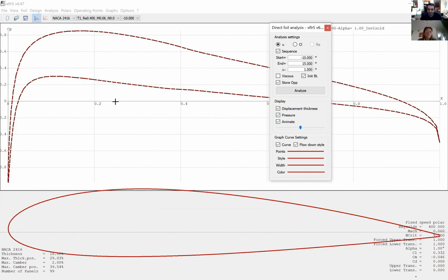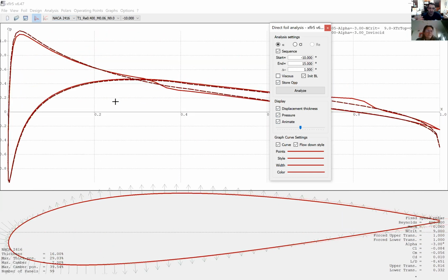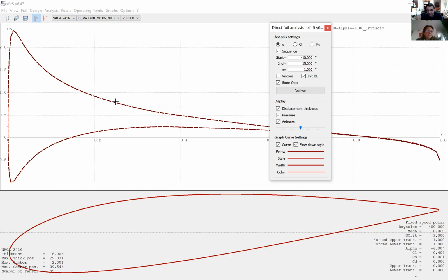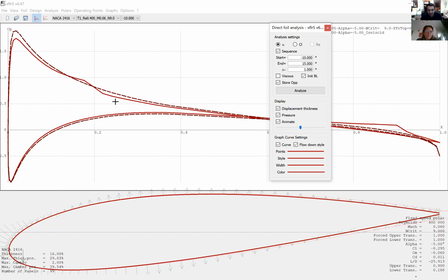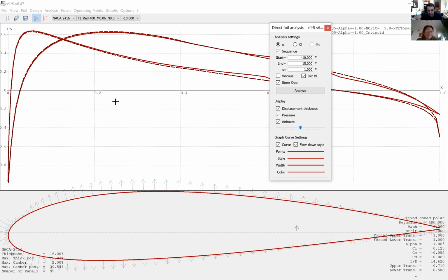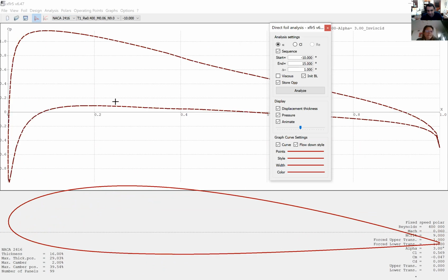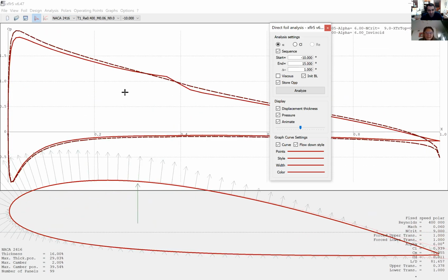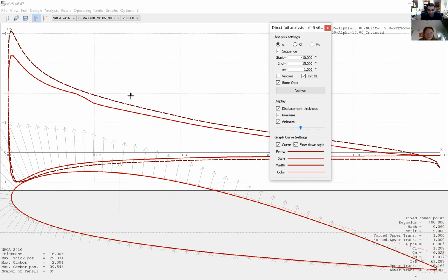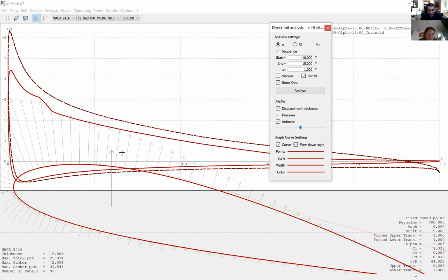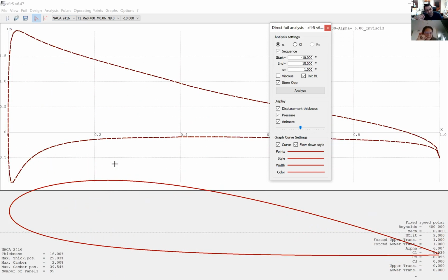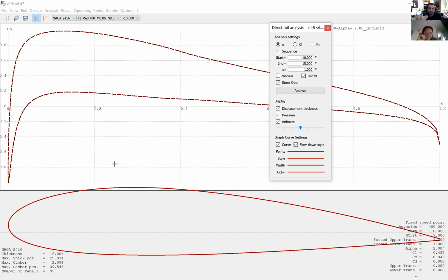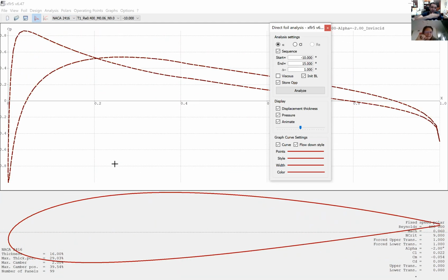With the angle of attack, the center of pressure, which is the resultant force or resultant pressure, is changing. You see that green vector at the middle of the airfoil. This is the resultant pressure, and its position is the center of pressure. So this is changing with the angle of attack of the airfoil, right?